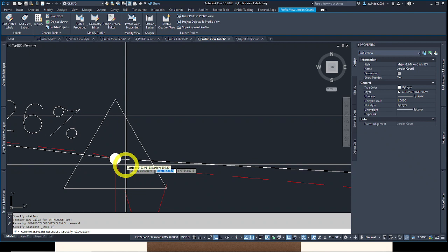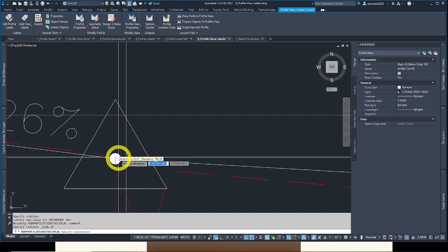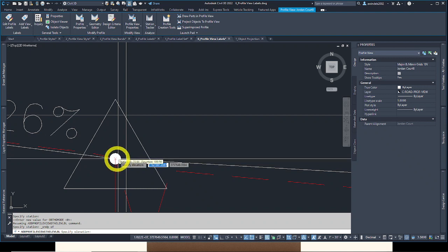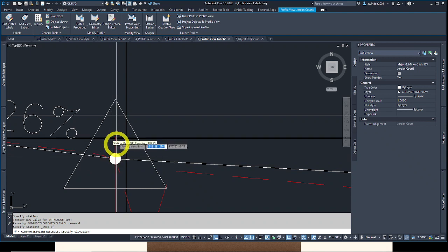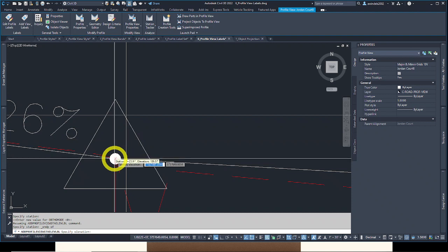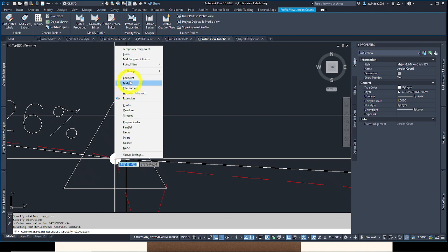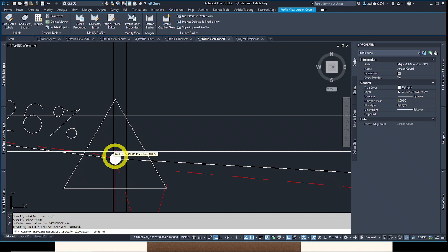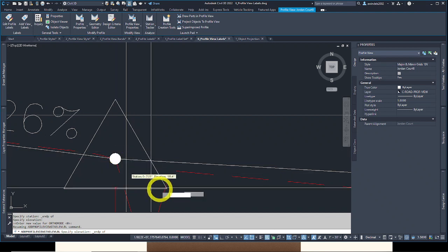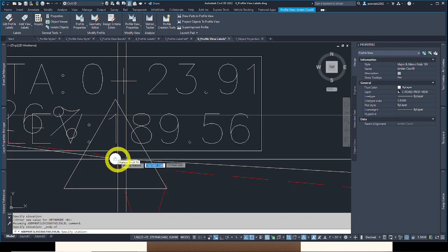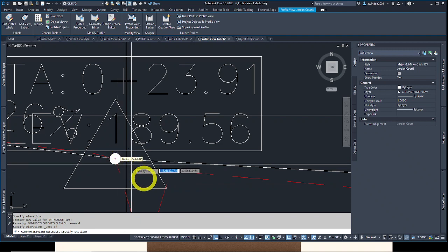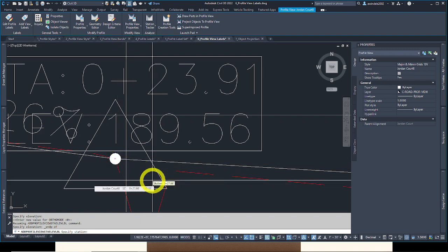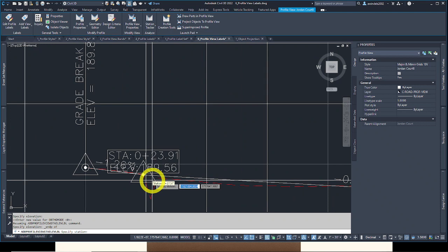And let's click it again in the same exact spot. So you've got to click once for the station and once for the elevation. So now I'm specifying the elevation in the Y. Kind of tricky. I'm going to hold shift plus right click again to say only endpoint object snap. And I'll select there. Didn't quite do it. There. Make sure you got that box going. The box or square means it snapped to the endpoint. I hit escape.